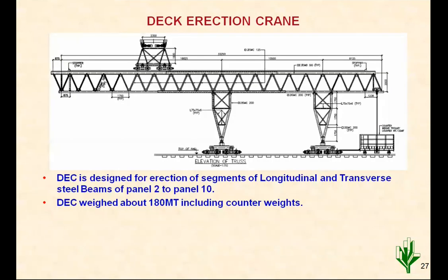This is a side view of the deck erection crane. That was weighing about 180 metric ton, including 30-35 ton of back weight. That is a counterweight for stability of this crane. So that was put on the deck.